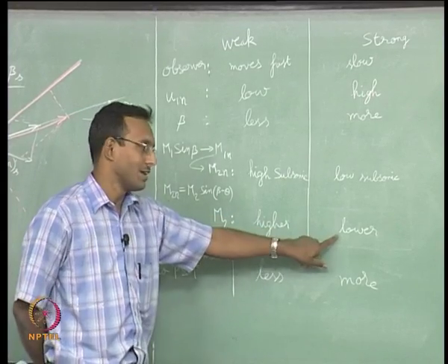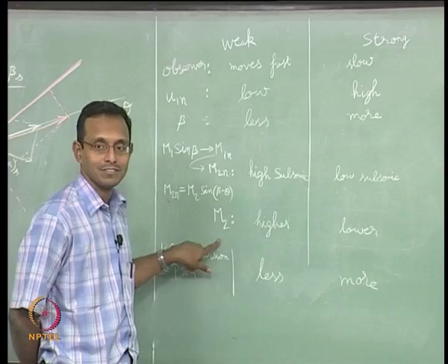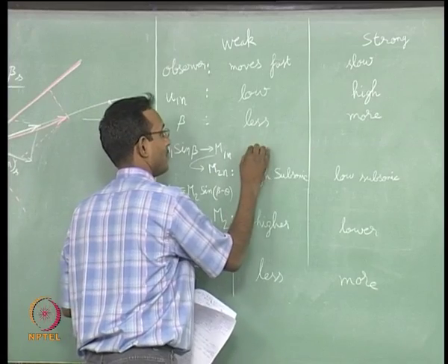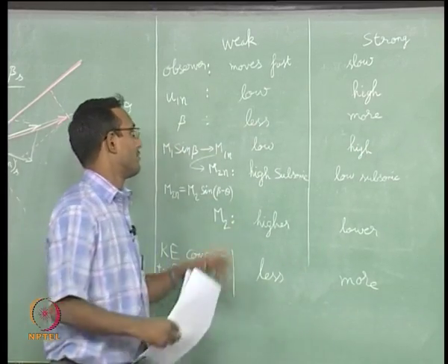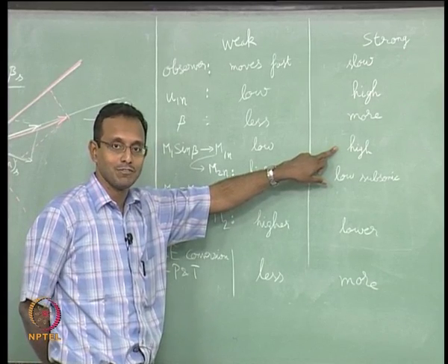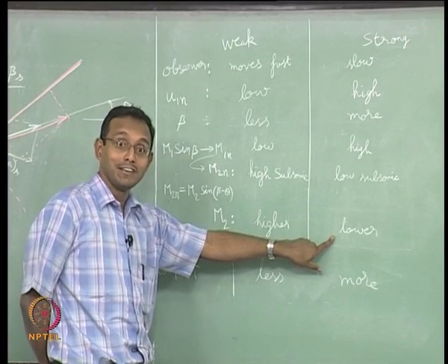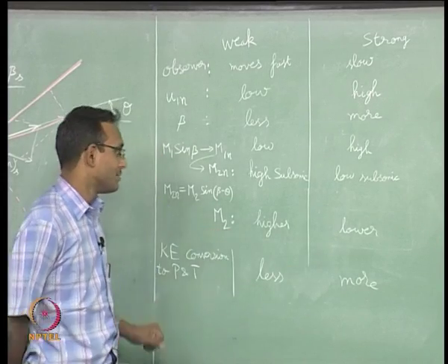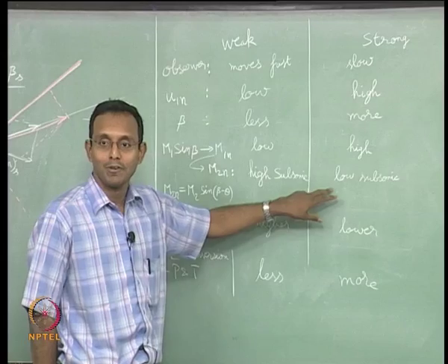I am putting it as normal in Mach number terms. Of course, you should know that temperature is also going to be higher, because M1 normal, maybe I should write M1 normal low, high. If M1 normal is high, T2 by T1 is higher. So the temperature of the flow behind the shock is higher, but the Mach number is lower, which means the velocity is really, really low. Which means I start with a very high normal component velocity and end with a very low normal component velocity.